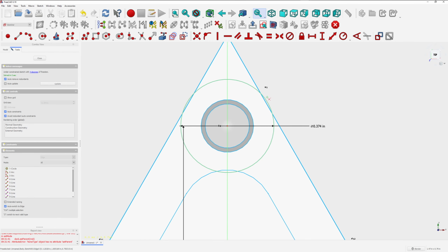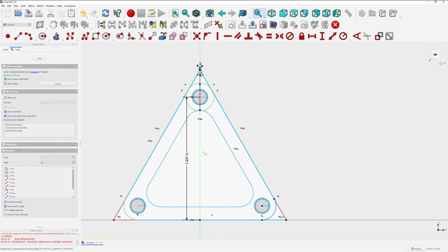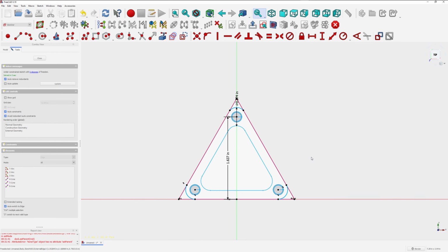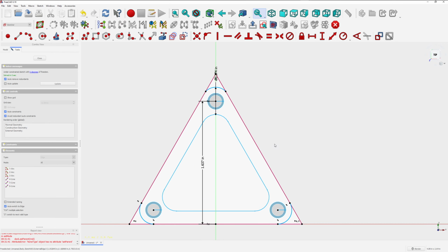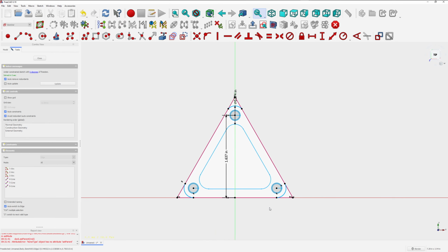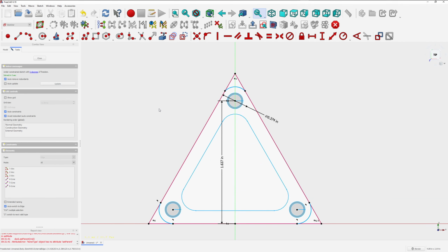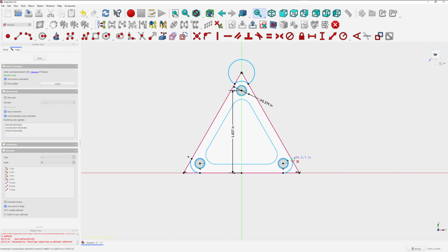And on this one, the circle goes just outside of the base part. So let's trim that outside part. And now we can just come in and delete this. And we can delete these lines now. So we just need these 3 arcs. So we're going to use this arc tool and select the endpoints of these arcs and draw this out. So let's do that for these 3.